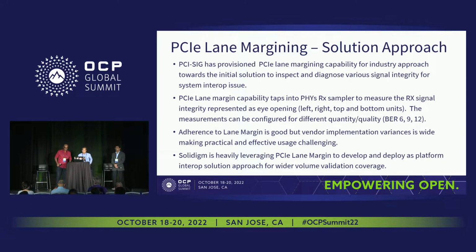Yes, with PCIe as the high-speed transport connection, transmission signal integrity is one of the main challenges to resolve. The signal integrity health is mostly the burden of the PCIe link receiver, and with many different IPs, there are many different proprietary methods to connect to the sideband to examine the RX health.